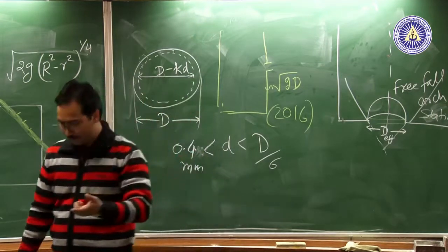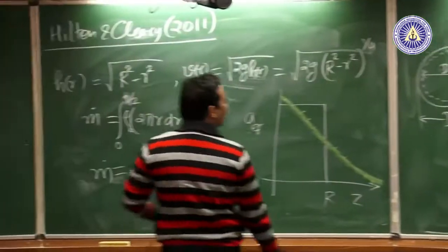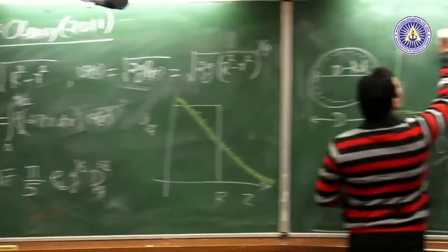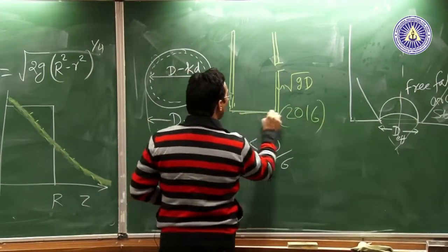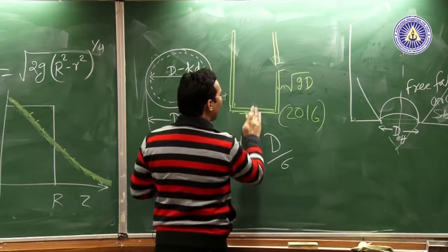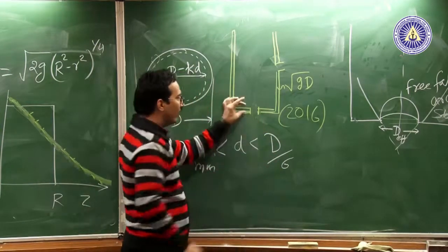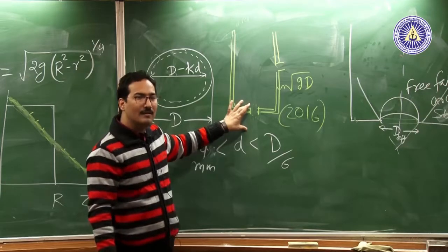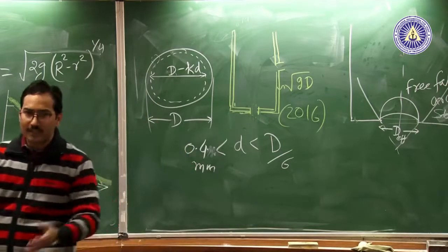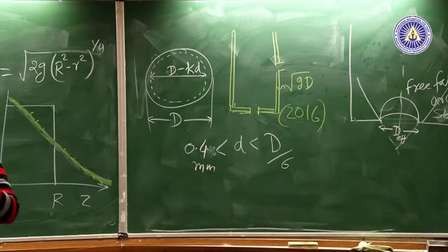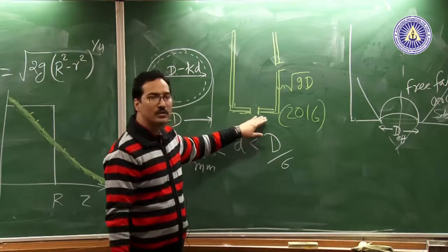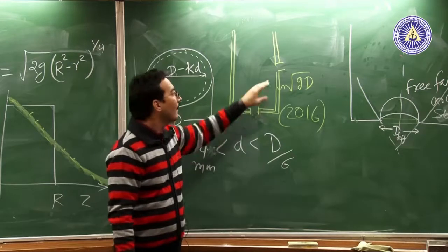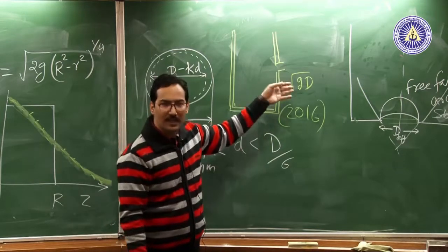Okay, let me repeat. My container thickness now seems to influence the flow, right? Which was not the case before. If I had a hole here, whether my container is this thick or that thick, unless you are really attaching a pipe there, where the grains start to experience no slip and air drag becomes important, which is a separate regime, otherwise you don't see much influence of the wall thickness. In this case, you do start seeing that.